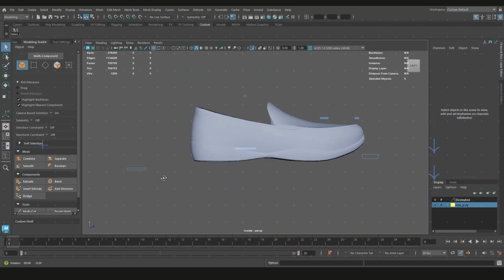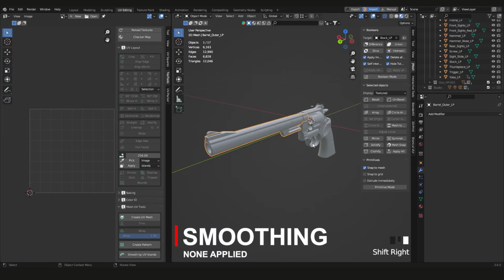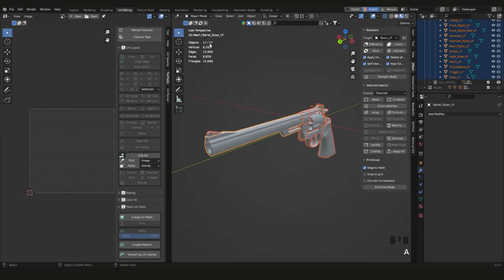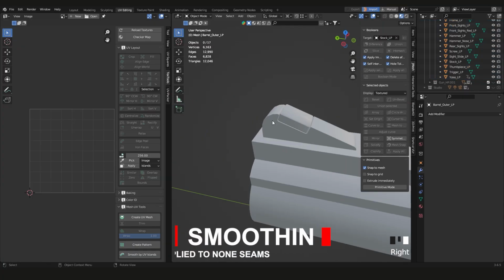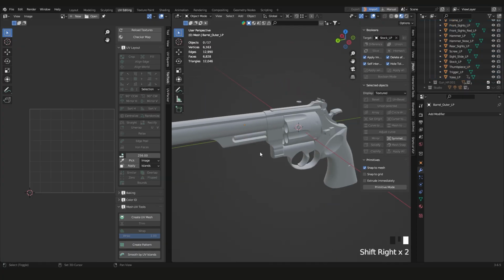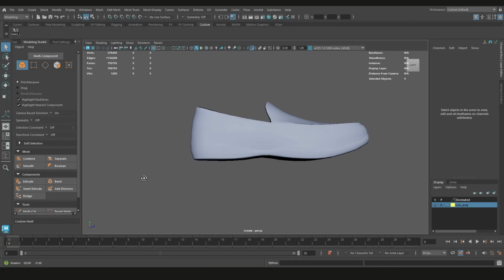Number nine, we aren't doing any hard surface stuff, so we won't need hard edge seams for our meshes, but as another general rule, remember that all of your hard edges are always UV seams, but not all of your UV seams need to be hard edges. Making these edges harder in some cases will help with your baking, especially with hard surface modeling, but in our case, we could have just softened everything and called it a day. We would have still been fine.